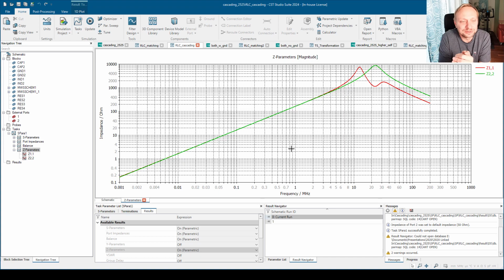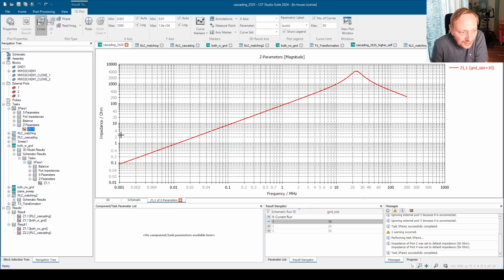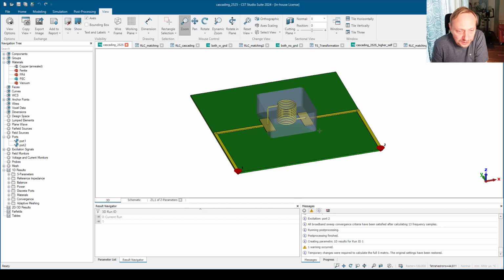And that's a very interesting case, and that's what I would like to discuss with you. The first and the most important thing is, of course, the measurement you are doing here. It's not only measuring the inductor, it's also measuring the traces, right? I didn't do any de-embedding here in this case. It's the raw touchstone from here to there.